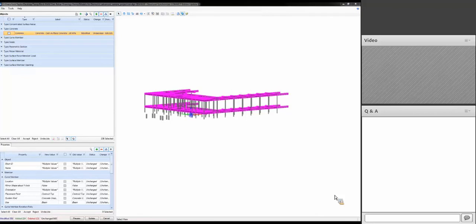and as you know, modeling in Revit or any BIM application, most often the case, you'll model the real-world condition, which means that the beam stops actually short of the column or short of the girder. So that tends to lend itself a little more towards being easier to start in the analysis application in RAM. Okay, I think that's what we're finding in general.